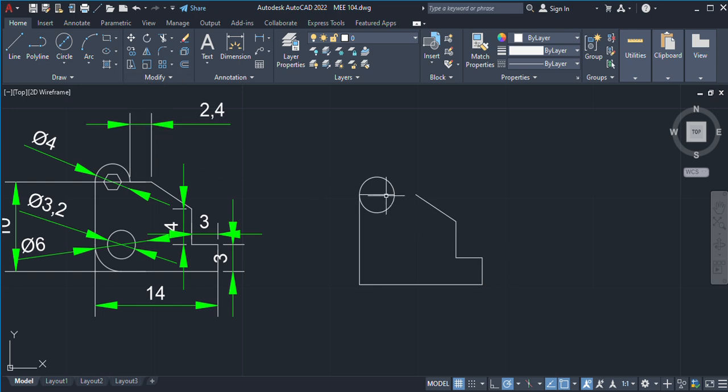You can just do it like this. I can pick like this. I'm stretching the line like this. So that's the work of this stretch here. You see, I did not go back to choose line, I just tap on it. So there are more shortcuts. It's better to know the shortcut for exam purpose. So just tap here like this. It will ask how much measurement do you want to extend your line? So that would be 2.4. You see like that.